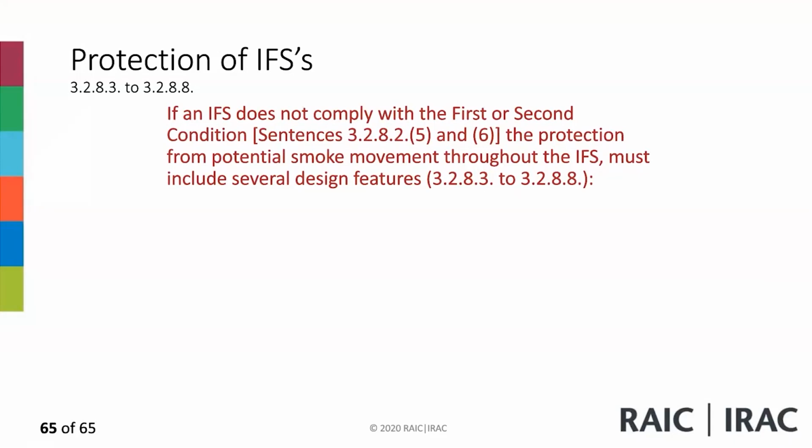In 3.2.8.2.3, if a closure in an opening in a fire separation would disrupt the nature of manufacturing process. So now you're in a plant, you have a manufacturing process. You need to have those openings, and for the process itself, the closure for the opening is permitted to be omitted, provided precautions are taken to offset the resulting hazard.